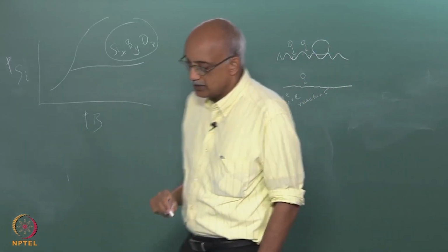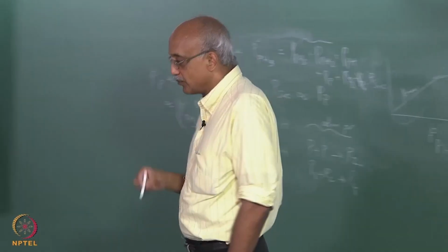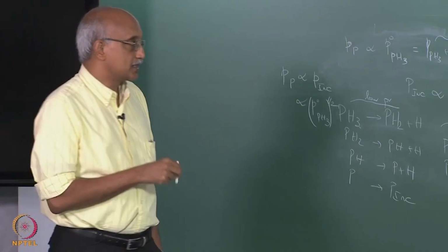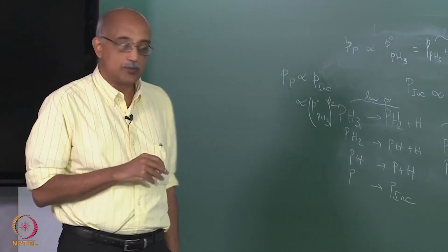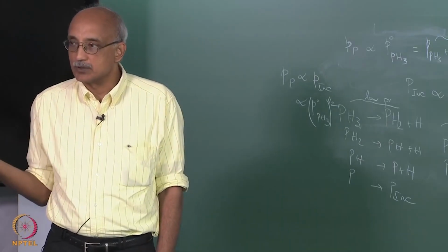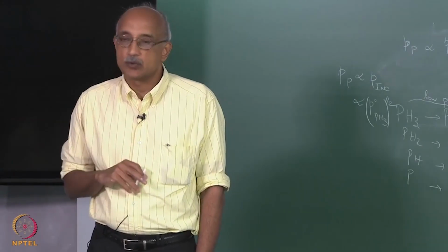You have to constantly be monitoring the thickness of the CVD film and providing the necessary adjustments to the operating conditions. You can do this either by changing the amount of reactant, or by adjusting the surface temperature. For example, you can just raise it by a few degrees to get a higher deposition rate and equalize it that way.